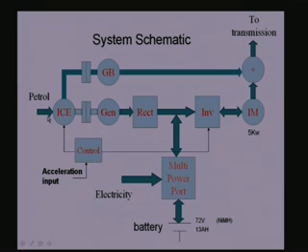So, the petrol is driving, let us say, an ICE, internal combustion engine, and the output of that is connected to a generator, alternator, which is rectified. Now, it is in the electrical domain, it is charging up the battery here, or it can go through the inverter and drive an induction motor to the wheels, or conventionally, it will drive an IC engine and through a gearbox, it goes directly to the wheels. That would be the way the general normal automobiles work.